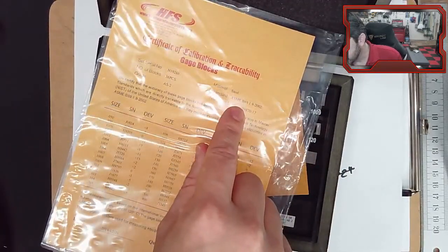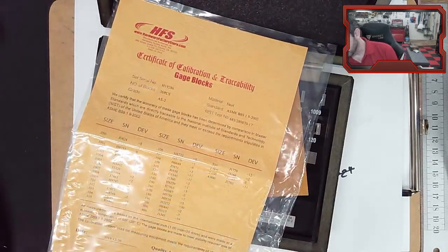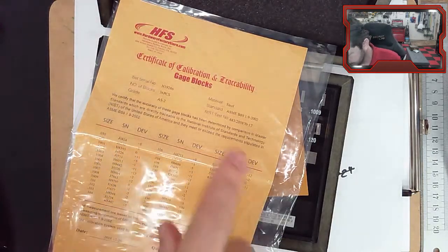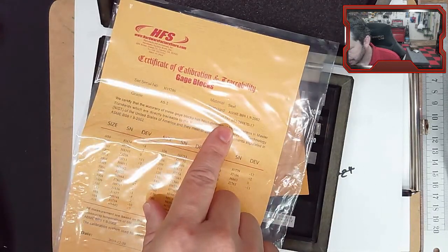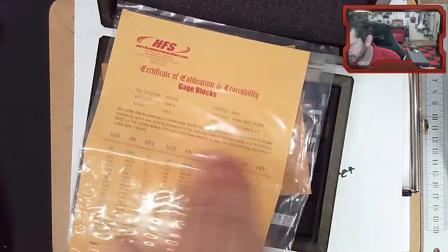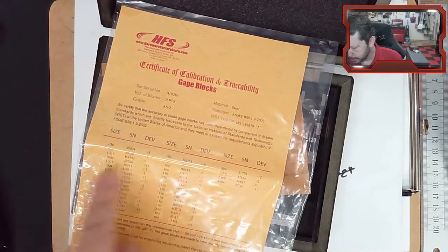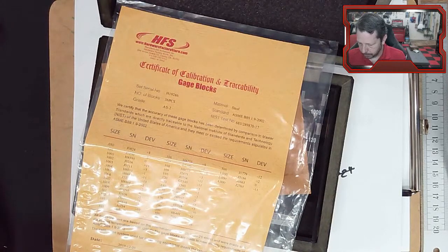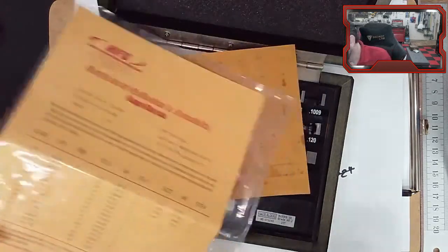It tells you what standard. So there's an ASME standard for gauge block calibration and gauge block tolerance and everything. And it says what standard they're trying to meet. And it shows the actual test number where this set of blocks was tested against that standard. And then this chart shows you, now these are metal gauge blocks. I'm going to use some gloves to touch them, just because oils from your skin can cause them to rust and everything.